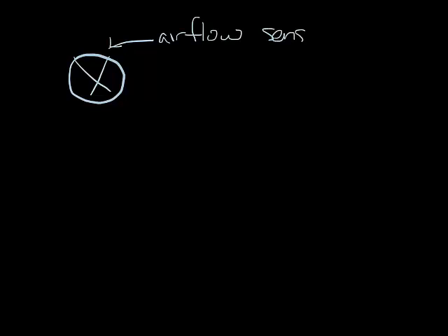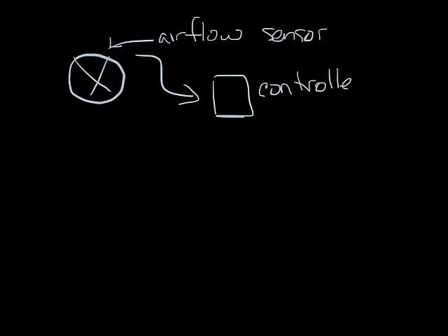Okay, so now let's look at pressure independence. In a pressure independent VAV box, the airflow volume is independent of the changes in pressure. So how does this work? Pressure independent VAV boxes have flow sensors that measure the pressure in the box and send this information to a controller. Now, using the equations we covered in the last podcast on pressure basics, the controller can calculate the airflow and control the damper to adjust for changes in pressure in the system.